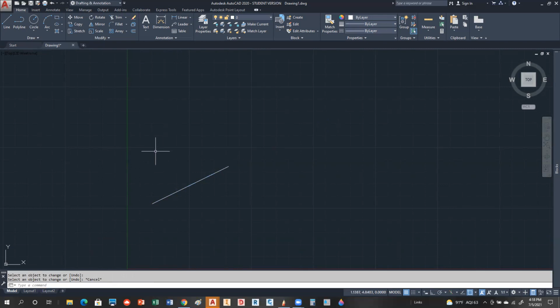So let's go into the lengthen percent option real quick. I don't use that one too much, but if I said percent and I want that to be twice as big, or let's say 50%, it's going to be half as big. Now watch, where I pick it, it's going to hold the opposite end fixed. So if I come here, notice it holds that end fixed, but what it's doing is dividing this in 2 and giving me that length right there.